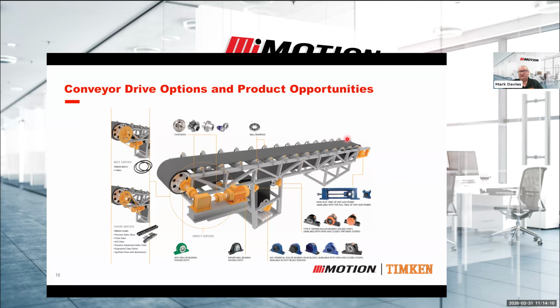In this case here, you'd have the product being loaded onto the conveyor through a chute at the tail or the rear of the conveyor, and then the direction of travel is uphill. In this case, it's an elevated conveyor, which most conveyors would be, and it moves up to the head, and then at the head, when it gets to the end of the conveyor, all the ore just flows off the end, and that goes into another chute, or it goes into a stockpile. It depends on what they want to do with it, but they all have the same layout.